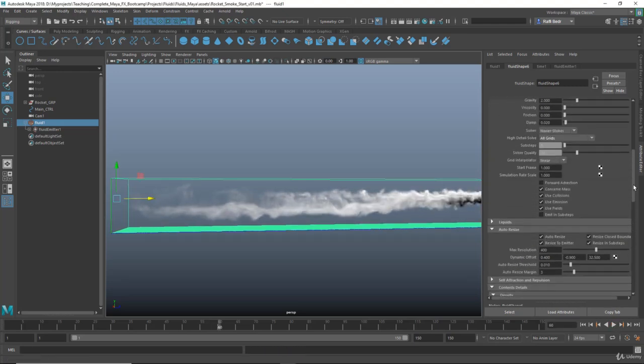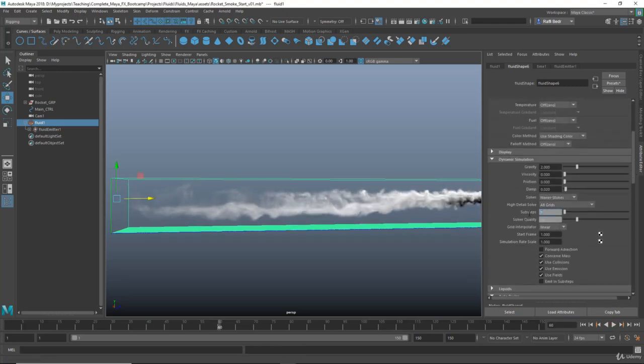And for the sub steps, here you see I left that to 1 and the solver quality is 22. Okay, so the substeps in Maya is really weird. So when you change that, the fluid behavior is changing completely. The substeps should improve the fluid behavior, not changing it. So you need to be careful when you change that. Really, you may have completely different results. So this is very important, okay?